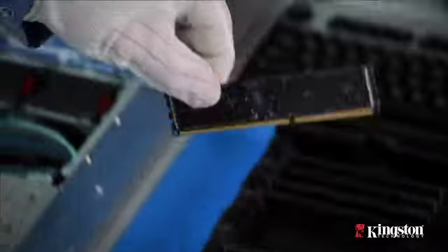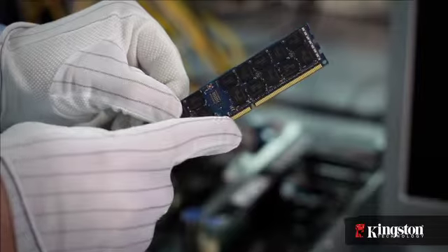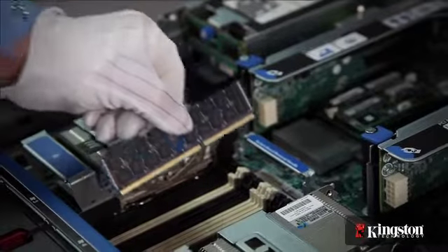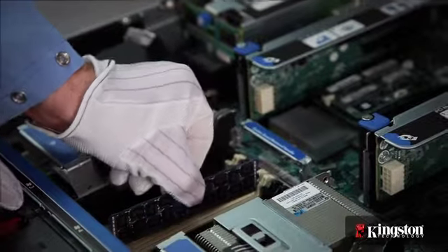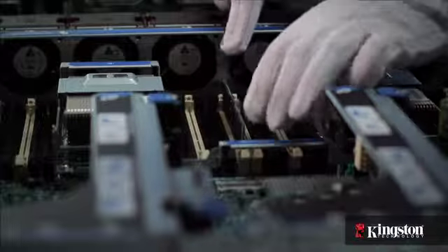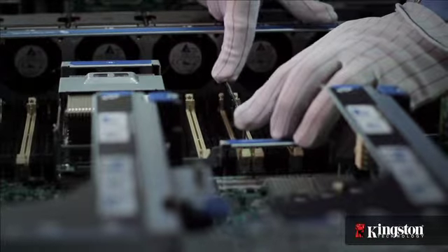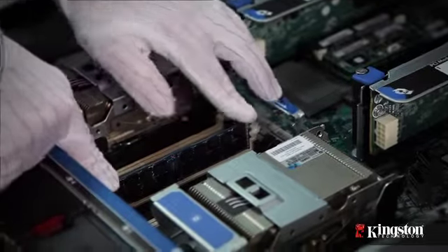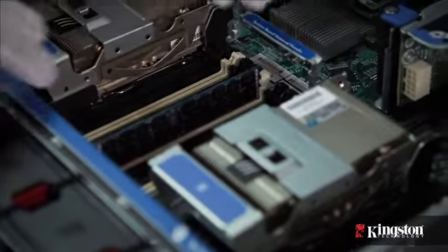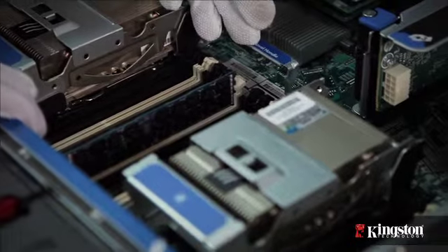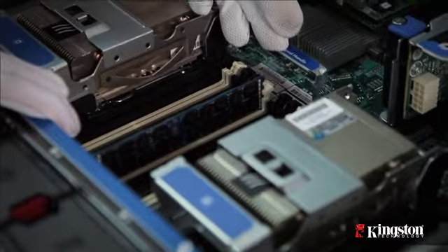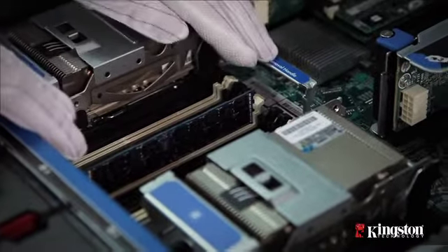When you install the memory, be sure the module key is aligned correctly with the socket. This will indicate whether you've properly oriented the module. When the keys are lined up, it's safe to press down into the socket. The clamps on either side will automatically fasten to the module when they're seated correctly. Be sure to press firmly to get a nice even seating.